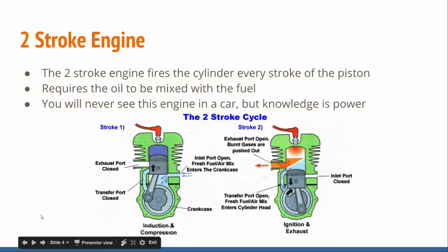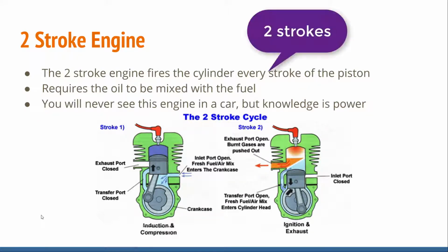The 2-stroke engine fires the cylinder every 2 strokes of the piston, hence the 2-stroke name. The 2-stroke engine requires oil to be mixed with the fuel. So it does not have a crankcase full of oil. The oil actually gets mixed in with the gasoline or with the fuel. So totally different. And I'm going to show you how it works.